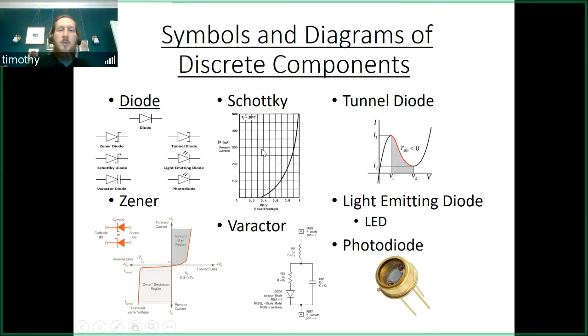And so this one, a lot of times, is very useful for getting rid of a low noise signal. Say you want to connect a push button, and you want to make sure that that push button is pressed in a solid manner before allowing the current to flow through. This will take off a lot of the debounce on it and make sure that there's a solid connection before it shoots that current through. So I've used these to make a one-shot circuit before, where it only goes off when it has that nice, strong, solid connection.